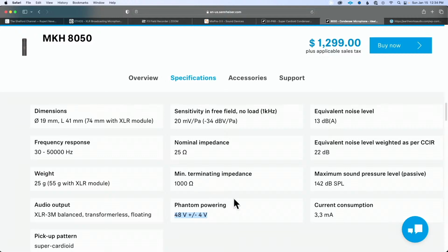I think that it's not that clear, but in any case, understanding the impedance is important there because you can make sure. There are mixers out there that have input impedances that are only around 1,000, 1,100, 1,200 ohms. So if you're using a microphone that has a 200 ohm output impedance, you wouldn't necessarily be achieving a full bridging impedance. So it may not perform optimally. It may not get the sound that you're expecting in those cases. So that's the reason it's important.